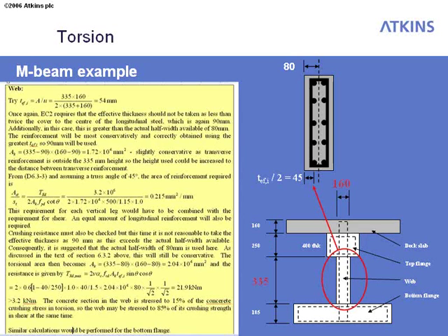And so when we come to do the design for the transverse reinforcement and the longitudinal reinforcement, even though making a wall thickness of 90 millimeters is a physical nonsense, we still have to use that to get the lever arm for the torsional flow in the right place. So we calculate an Ak based on the section dimensions and a wall thickness of 90 millimeters. And if we choose the same truss angle theta of 45 degrees in both directions, we end up with the same reinforcement in both directions.